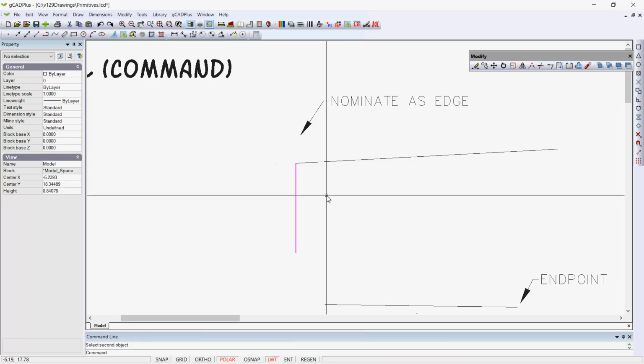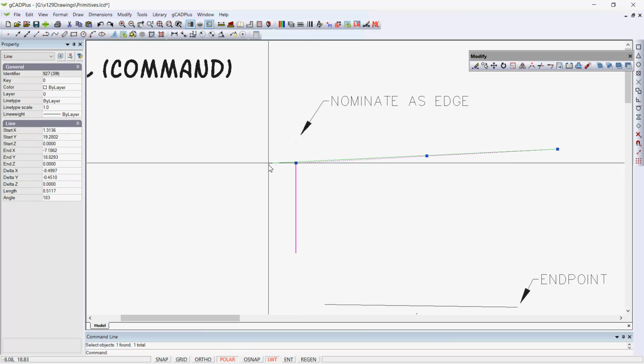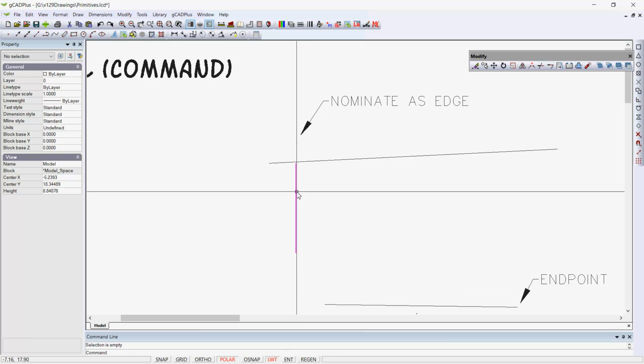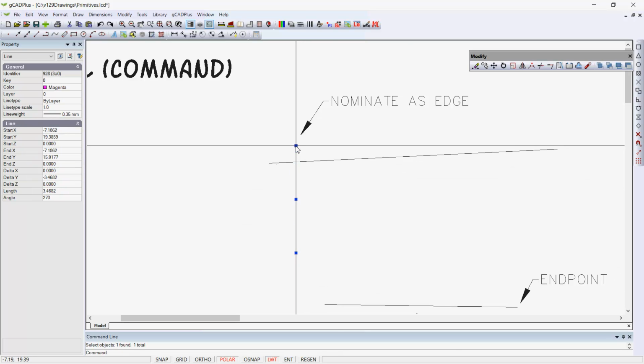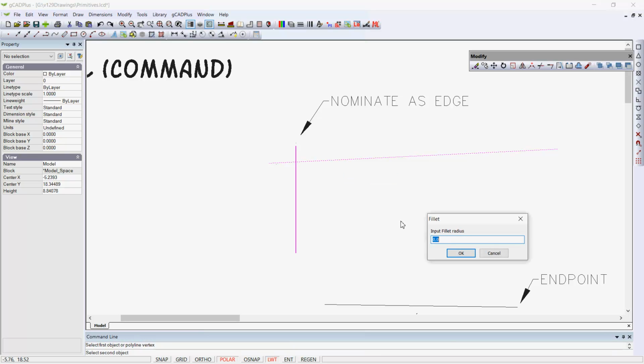The important thing is, let's undo, and we'll have those. Whoops, we can't actually undo the way I want it to undo. We need perhaps one day to just modify that undo so that we could get back to our lines that hang over like so. Let's repeat that fillet command, and we're asked to select the first object, so we'll do just as we did before, but I'll right click. See, we can set a radius at this point. Because we set a radius of 0, which is the default, we neatly trimmed both overhanging pieces.